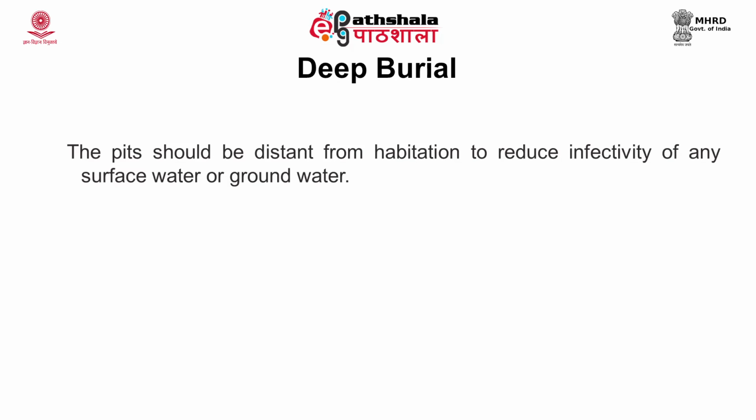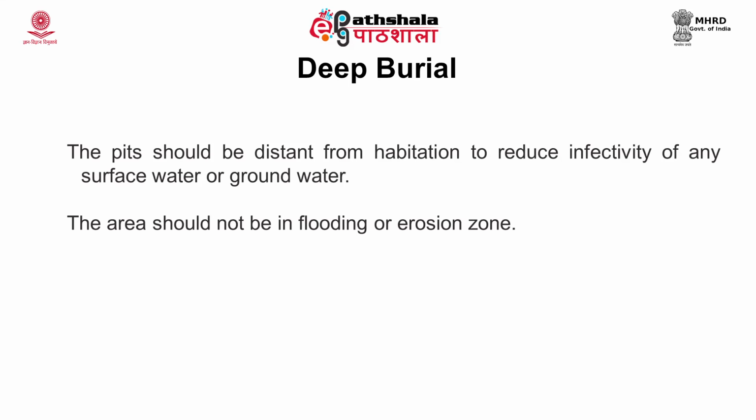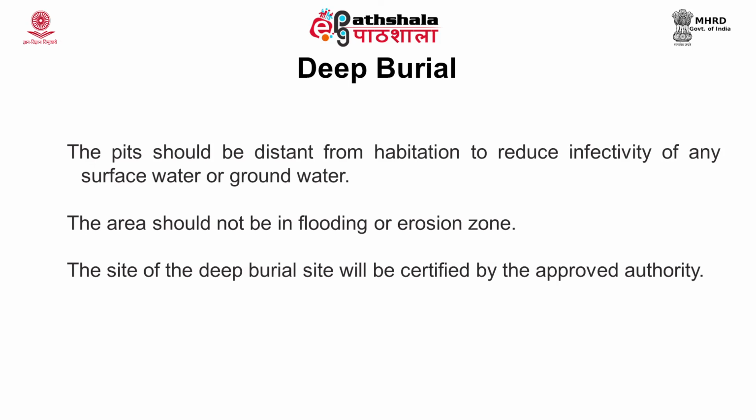The pits should be away from the habitation to reduce infectivity of any surface or groundwater. The area should not be in a flooding or erosional zone. The site of deep burial should always be certified by an approved authority.